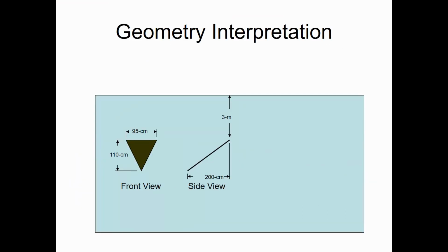All right. So just as a beginner, let's say we have a submerged plane, and it's triangular in shape. Just to get a refresher on how we interpret drawings like this, remember that when you see something from the front view, you don't necessarily get the height of the object if it's inclined, like this one is. So why don't you take a moment and try to calculate the dimensions of the triangle, meaning the length of the triangle and the width of the triangle's base.